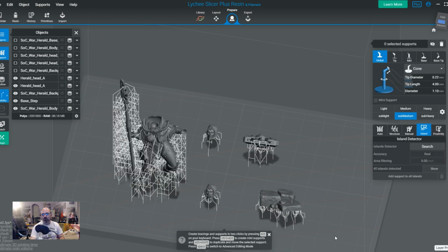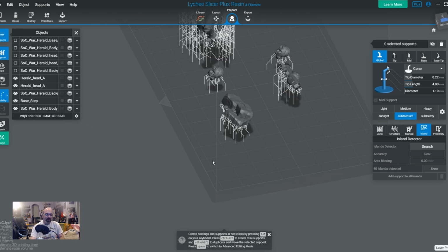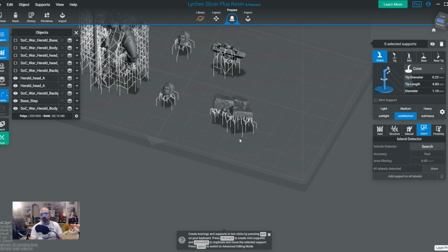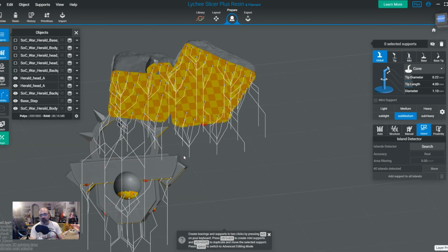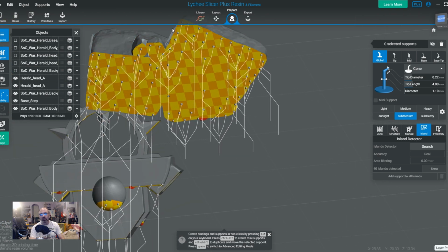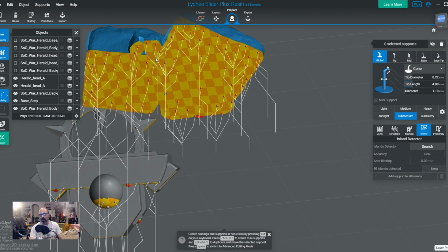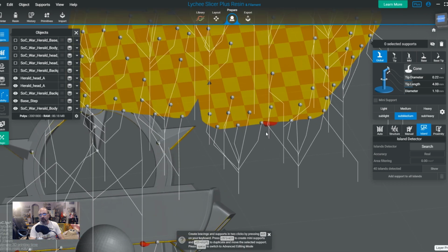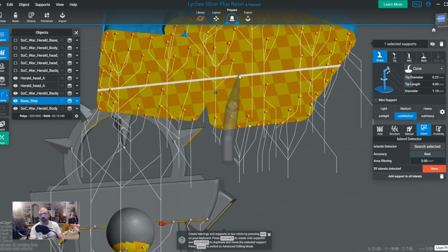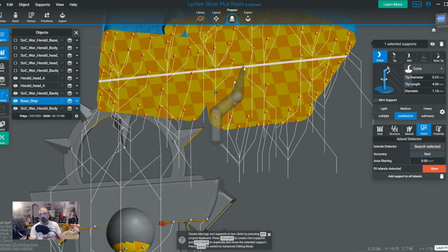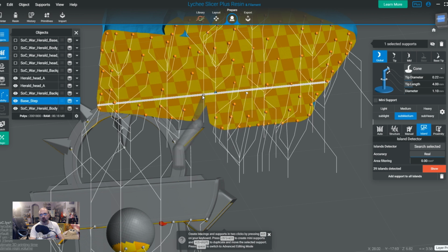Another common fail problem is when people are faced with objects with flat surfaces. People will oftentimes simply do a perimeter run, and they won't do any supports in the middle. Now, this one obviously has some islands that still need addressing, but it's supported pretty well. There's a couple gaps in the middle I would probably fill in personally, but for the most part, at least there is more than just the perimeter.